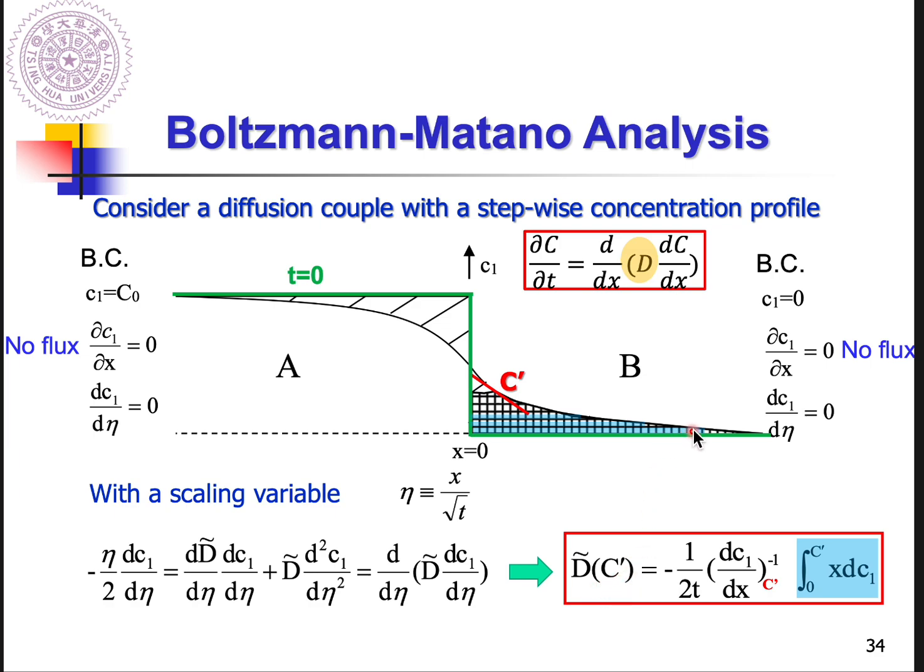That also implies that as long as we have the diffusion profile of diffusing atoms at each location, we get a different interdiffusivity, because even with the same diffusion time period, the slope and the integral term are different.